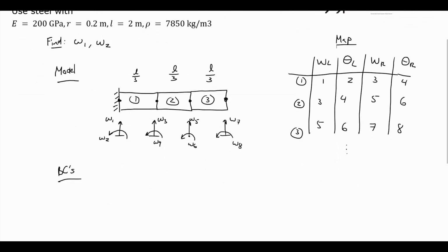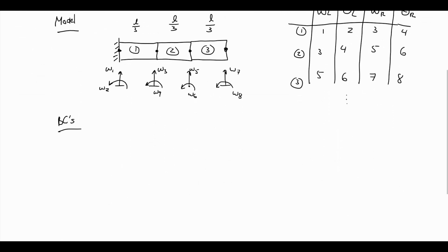So in this case, looking at our small scale model here, we are going to see that W1 is always 0 because the deflection at the wall is always going to be 0. It cannot move up and down. And also we're going to see that W2, the slope at the wall, is always 0. It cannot be a non-zero value. Now, when we did this analytically, we had two other boundary conditions at the free end, but those were on the internal bending moment and the internal shear force. So again, nothing in the finite element code needs to be changed for those boundary conditions.